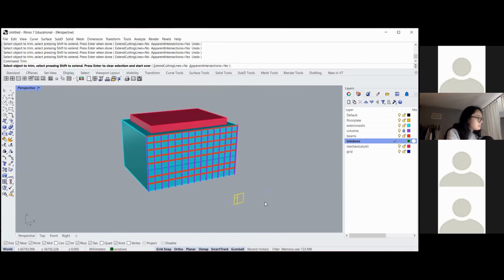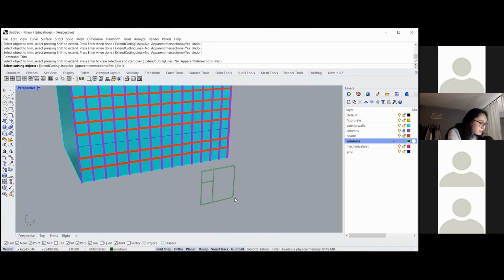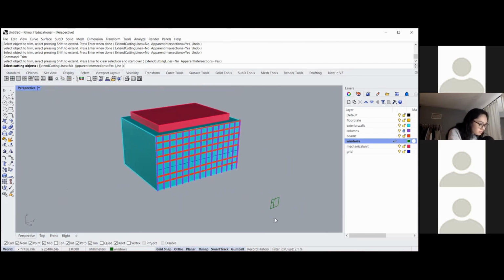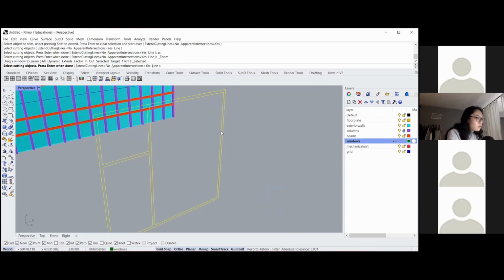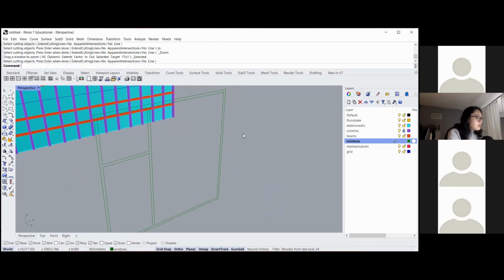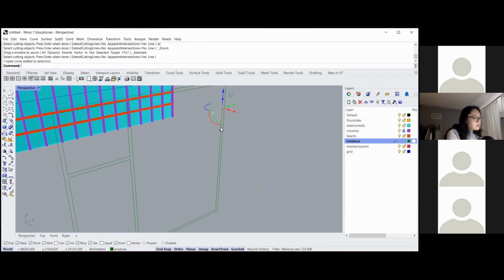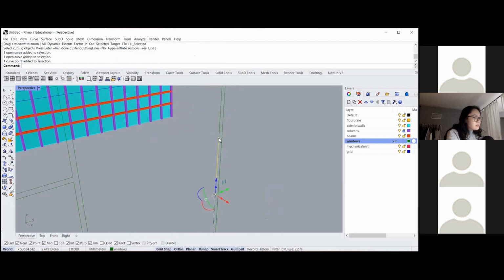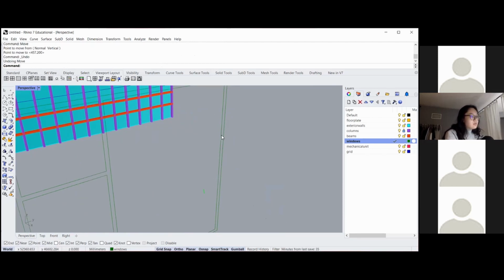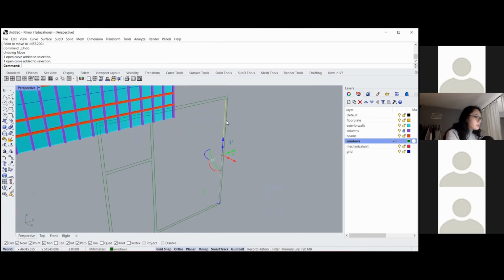And then you can see that, hold up, let me zoom in. You can see that there's a little hole where there used to be kind of this frame. So there's 2 ways you can fix that. You can select the point of the curve and move it like that. You can also extend like we did before, or it should work to run close curve.